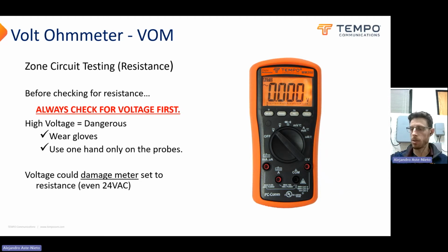That said, one great thing about our pocket multimeter, our PM100, is it starts up in auto mode, which takes resistance readings by default. So here I'm just getting 0 ohms, obviously. However, if you touch something with voltage, it's not going to take resistance readings. It's going to tell you the amount of voltage. So it does that work for you. Not only that, but it will tell you whether that is AC voltage or DC voltage and the appropriate amount of voltage.